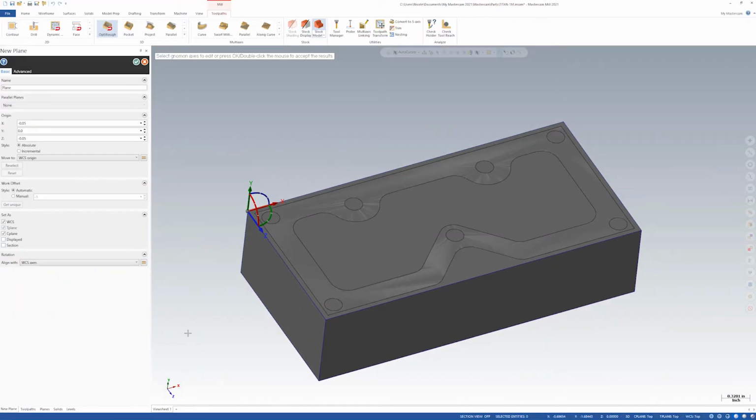You might be asking, why did we do the back left edge? The back edge of your vise is usually going to be a fixed point. It doesn't move, and so any features that are machined based off of that back edge are going to be a lot more consistent, and it'll be easier to adjust your offsets, to get things into tolerance if you're basing it off of a fixed point like the back jaw. You could do the back right edge, you could do the center. What really matters is consistency. We always shoot for back left edge.